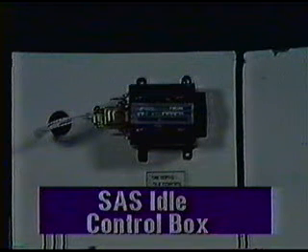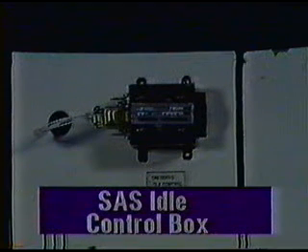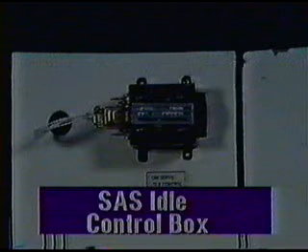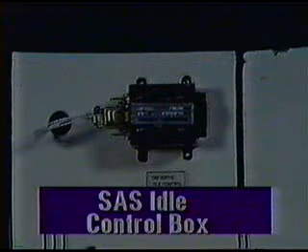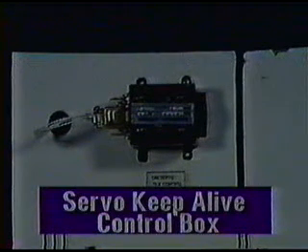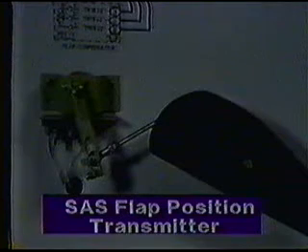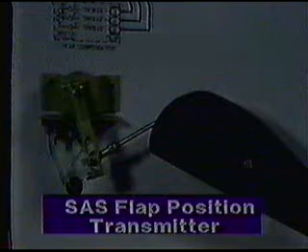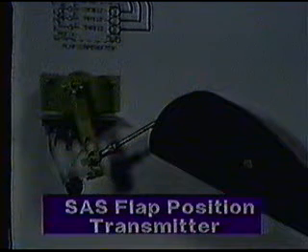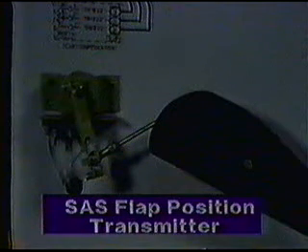The control box, located in the right-hand side console, is called the SAS idle control box, sometimes referred to as the servo keep alive control box. The potentiometer installed inboard of the left-hand flap is the SAS flap position transmitter, sometimes called the flap follower.